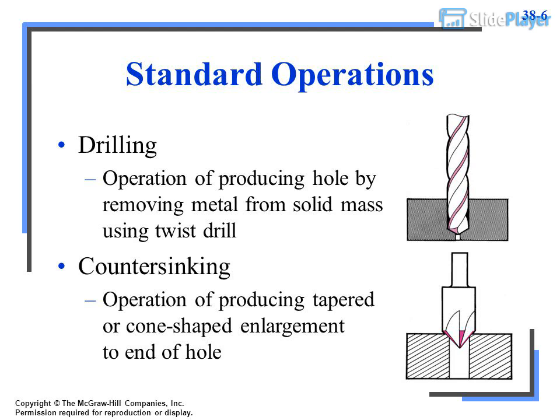Spot facing, figure 38(1)e, is the operation of smoothing and squaring the surface around a hole to provide a seat for the head of a cap screw or a nut. A boring bar, with a pilot section on the end to fit into the existing hole, is generally fitted with a double-edged cutting tool. The pilot on the bar provides rigidity for the cutting tool and keeps it concentric with the hole. For the spot-facing operation, the work being machined should be securely clamped and the machine set to approximately 1/4 of the drilling speed.